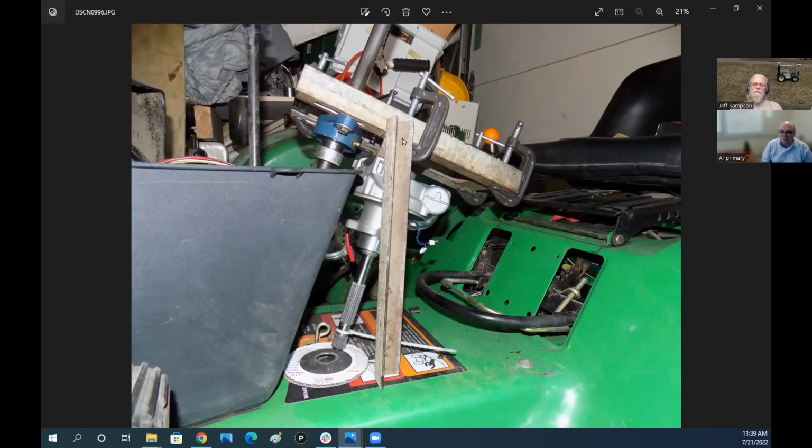Did you ever consider welding instead of drilling a hole in that uniframe? Just welding a bracket across that and then bolting down here at the bottom. Yeah. I hadn't thought about that. I think this is steel, so I suppose that would work. I mean, I know you always wanted to be able to return it to normal condition, but yeah, that would be an option as well. And if you just, instead of welding it all, just welded on the bracket and then had holes in the bracket that you could bolt to, yeah.